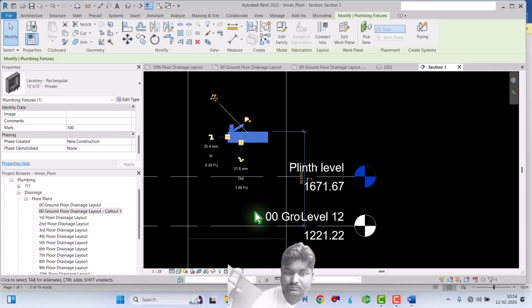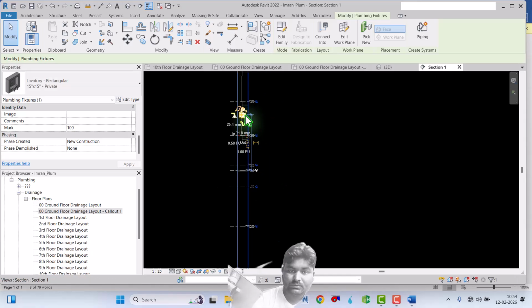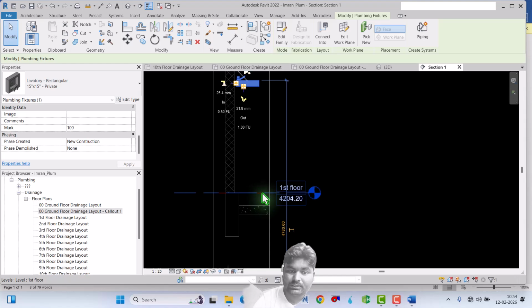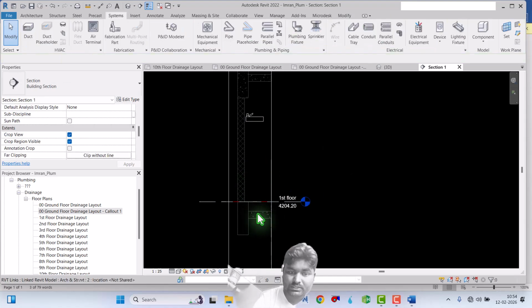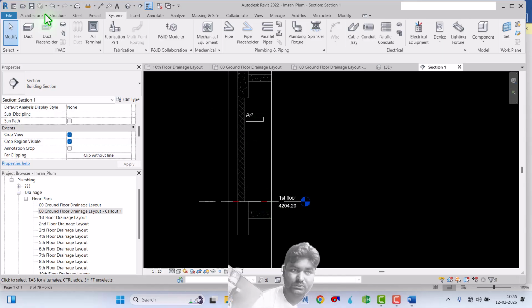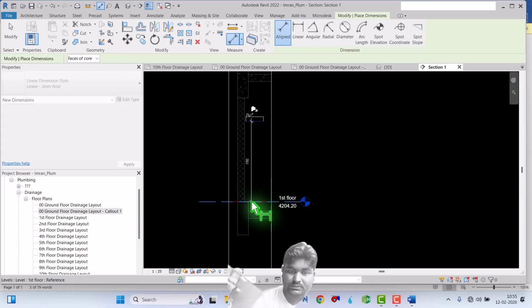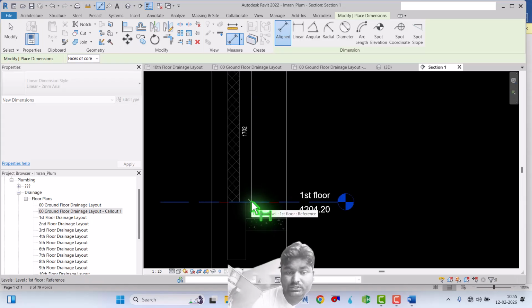See, select this one. Either you can use the arrow button up, click Shift and arrow button up, or here already. Okay, so what is the standard height? Standard height is generally we consider 800 or 600. Okay, but it should be 600 to 800. Between this you can place our wash basin. Okay, as per the standard. So what is here? Length, see, it is 1700.